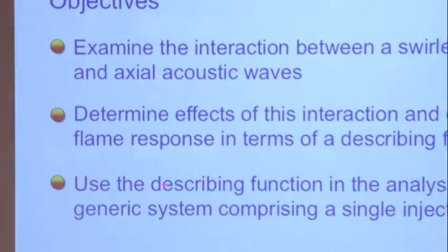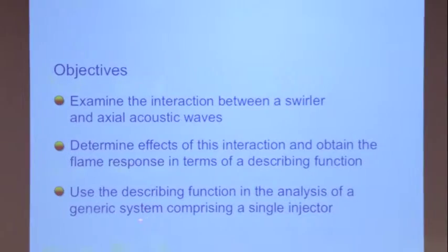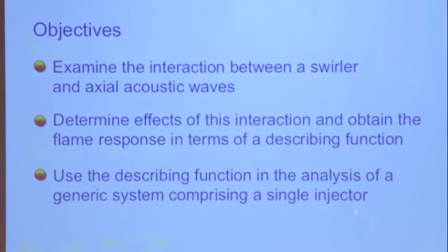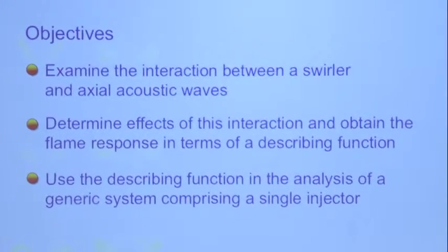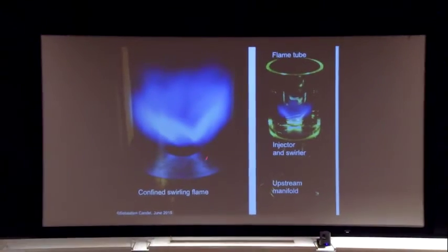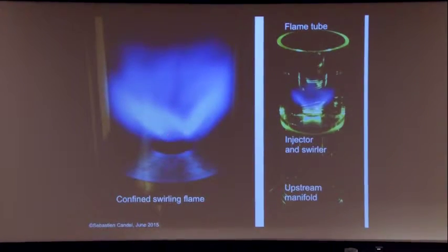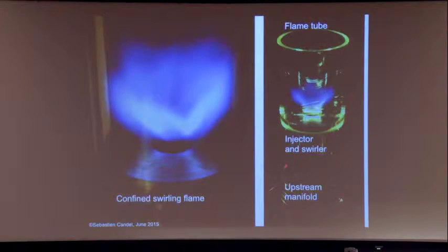So what we want is to examine the interaction between the swirler and acoustic waves, determine effects of this interaction, and obtain the flame response in terms of describing function. Use the describing function in the analysis of generic systems comprising a single injector. So this is a typical swirling flame in confined. This is another one. This is the upstream manifold. We use the same burner, but now it is equipped with a swirling system.